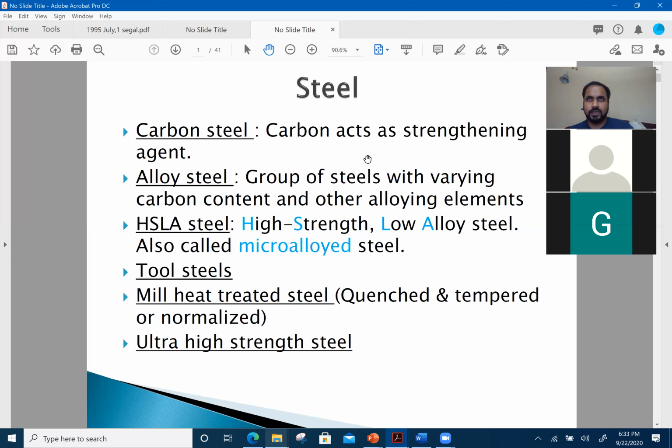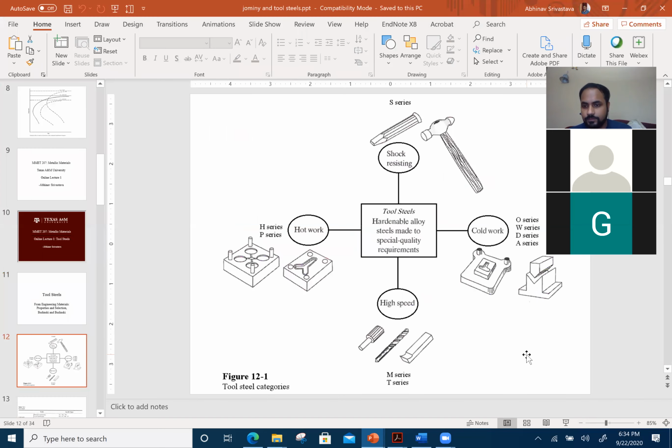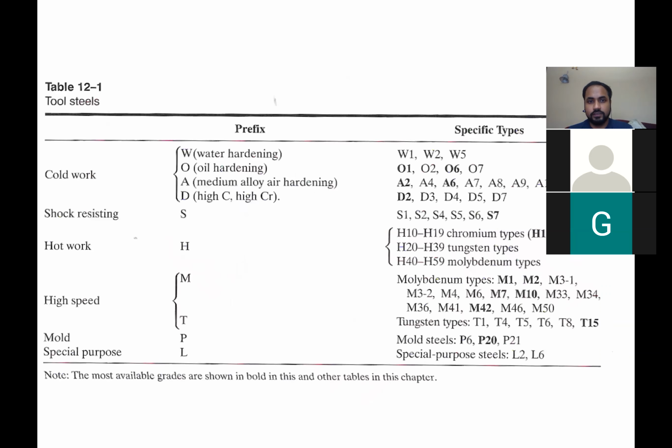And then I think some of the tool steels are really helpful. I didn't discuss that part, but there are a few tool steels here. There are some tool steels which are shock resistant. It is used for making hammers. So I would say look into shock resisting tool steels. Basically, any tool steel that starts with an S in the name is a shock resistant tool steel. So it can be S1. I have S7. I had a small rod of S7.